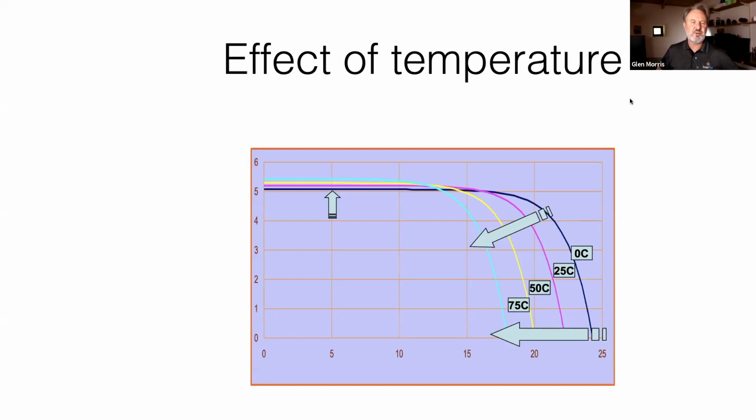Incidentally, this is a bit of a trick with some of the solar panel cleaning companies. They often say, look how much better your system is after we've cleaned it, while they're hosing it, and the panel power goes up and you get all excited, and you take the hose away and the panels warm up and the power disappears again.